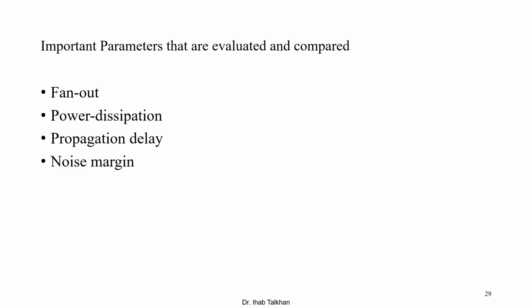So sometimes if you have different devices in series, this means V1 multiplied by I1, then V2 multiplied by I2, then V3 multiplied by I3, and so on. Sometimes the voltage multiplied by current will give you a power which is not enough to operate the fifth or sixth device. So actually, this is what is meant by fan out. The maximum number for the digital system to feed different gates from one output is actually 8 gates. You can feed 8 gates, and then you can use a buffer for the other units and so on.